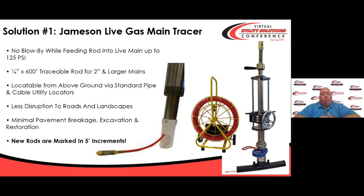This is locatable from above ground after it's inserted into the pipe using standard cable and pipe utility locators. Through this process, you can avoid major disruptions to roads and landscapes. You do have to dig and expose the line once, and then as you move down the line, you have to expose, but you're doing so in planned and manageable locations.